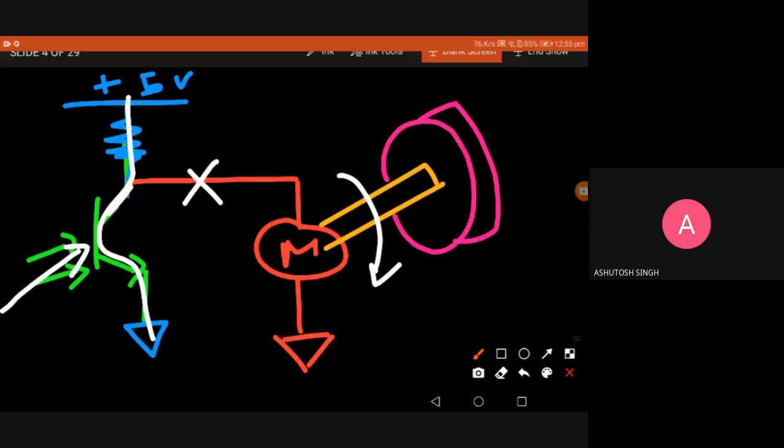Similarly, if I make a circuit for the opposite wheel, right or left wheel, whatever, for both wheels, I'm designing a complete system which is working based on my photo sensor or photo transistor input. Whenever the light is coming to the base, the motor is off. Whenever there is no light in the base, the motor is running. Although I am giving you a simple application, and this same circuit is not designed like that, for all practical understanding, for application understanding, I'm explaining in a simple fashion.